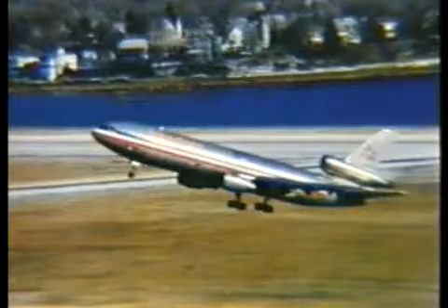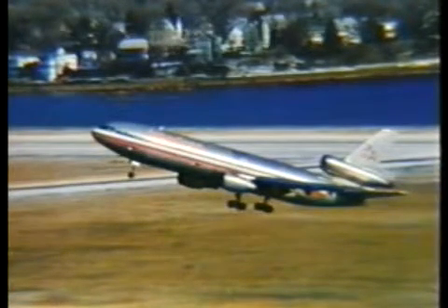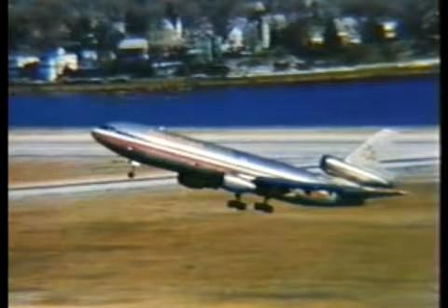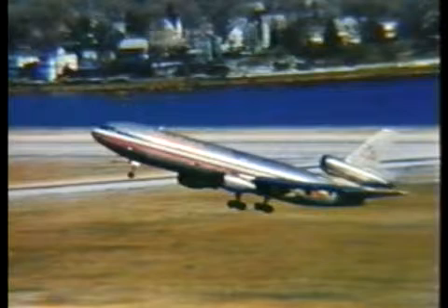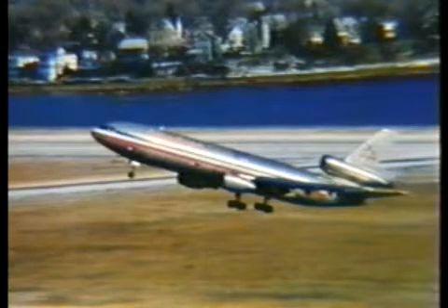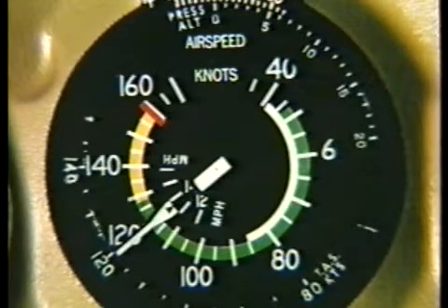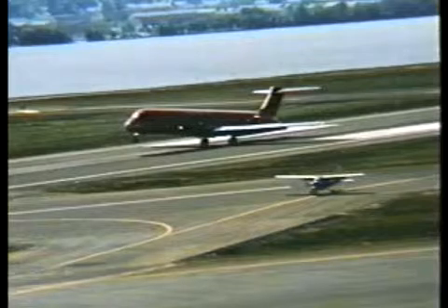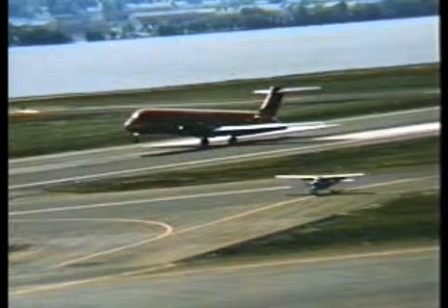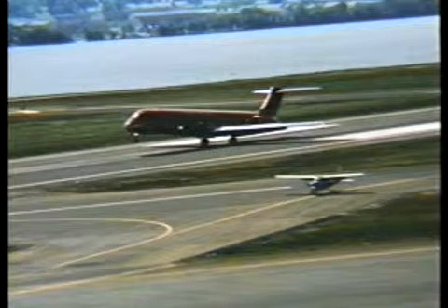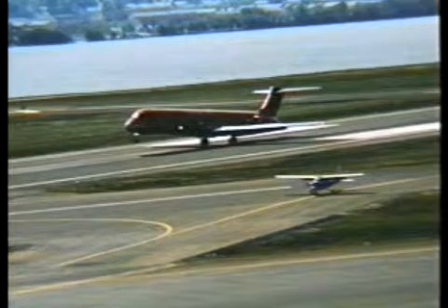Obviously, you can see that in order to make precision landings, you've got to be on the ball. And that goes double at a busy airport, because traffic flow may dictate the need for you to carry extra airspeed on final, or shift your aim point. You see, you're almost never the only airplane out there, and you've got to remain flexible to work within the system. A controller may ask you to stay well above the normal traffic pattern, or to maintain cruise speed until you're on short final. And then he might come back and ask you to land short and clear at the first available intersection, things that you were taught not to do back in flight training.